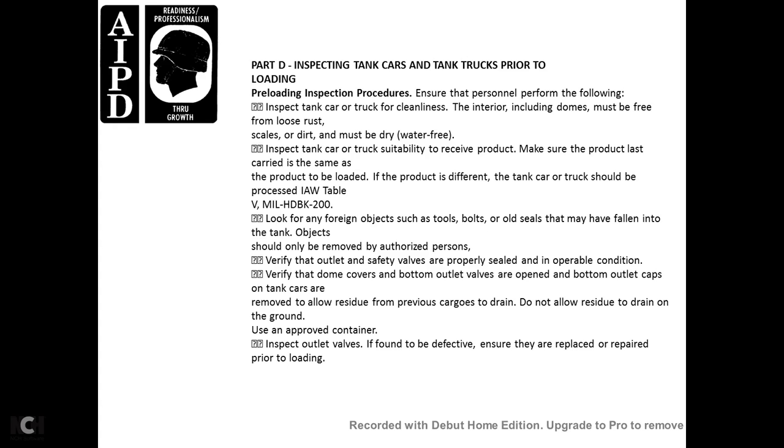Part D, inspection of tanker cars and tanker trucks prior to loading. Pre-loading inspection: ensure that the personnel perform the following inspections. Tanker truck cleanliness, including the domes, must be free of loose dirt, scale, and dirt, and must pass a dry, water-free inspection. Tanker car and truck suitability to receive the product: make sure the product last carried is the same as the product to be loaded.